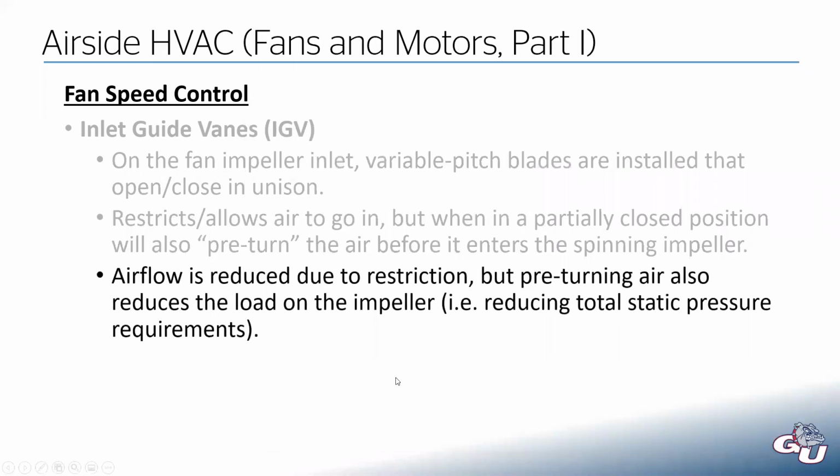And what that does, well, it does two things. As those close, that does create a restriction. So that does reduce the amount of air that's going to go through that fan. But at the same time, as those turn and create that restriction, they also take a sharper angle and pre-turn the air more.